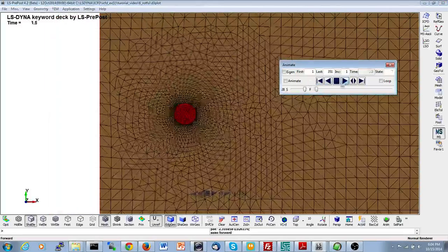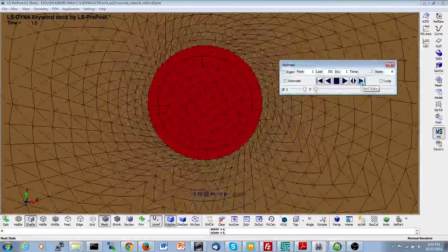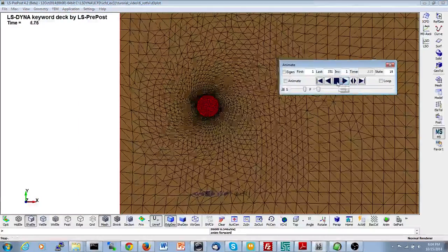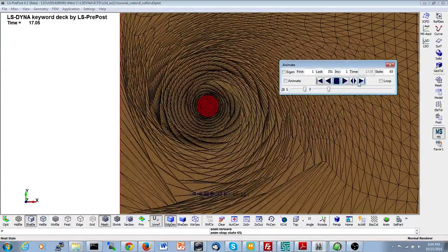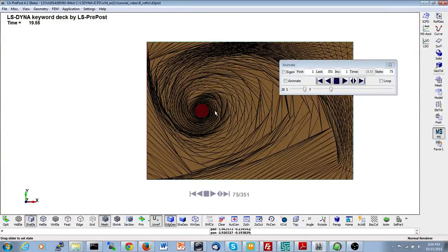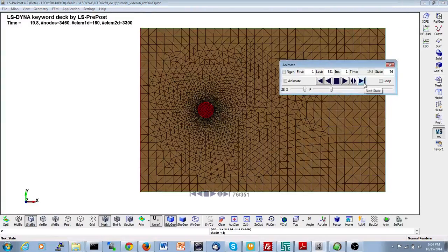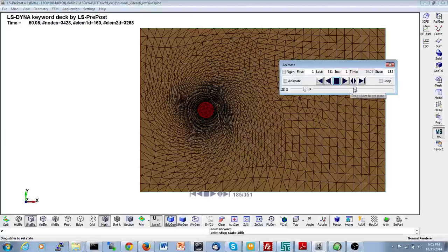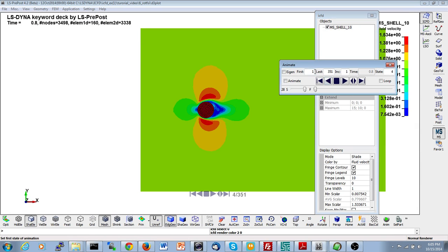If I keep something like that, see, oh, now we see our solid starts spinning, and the fluid mesh follows the solid's rotation, and so also starts to spin, and of course it starts to distort more and more until you get this very ugly behavior, but still the solver does not crash. And once something happens, the solver will automatically remesh, start deforming again, remesh, start deforming again, and so on and so on. So obviously in those cases the solution is probably not to be trusted.